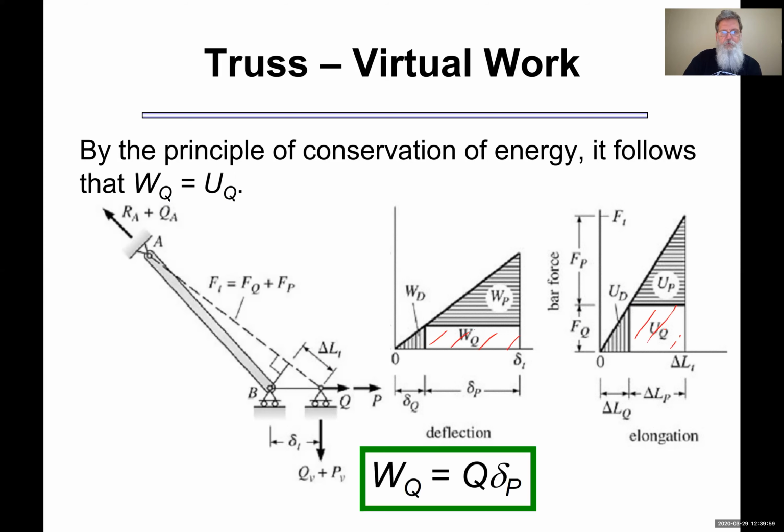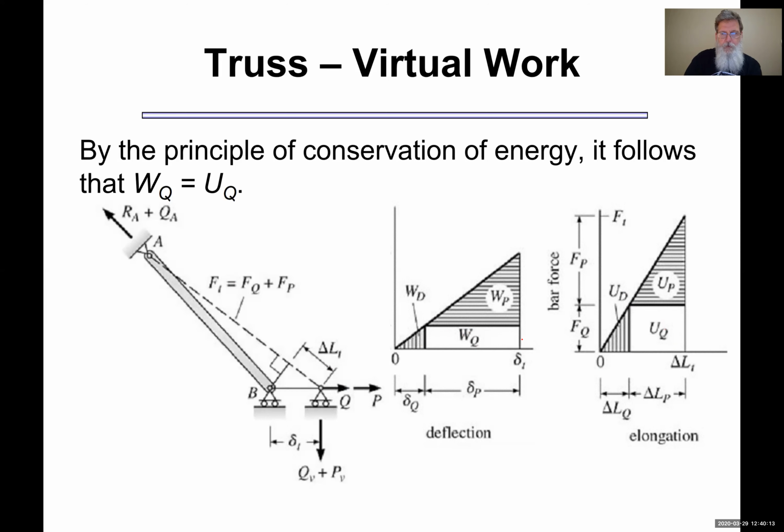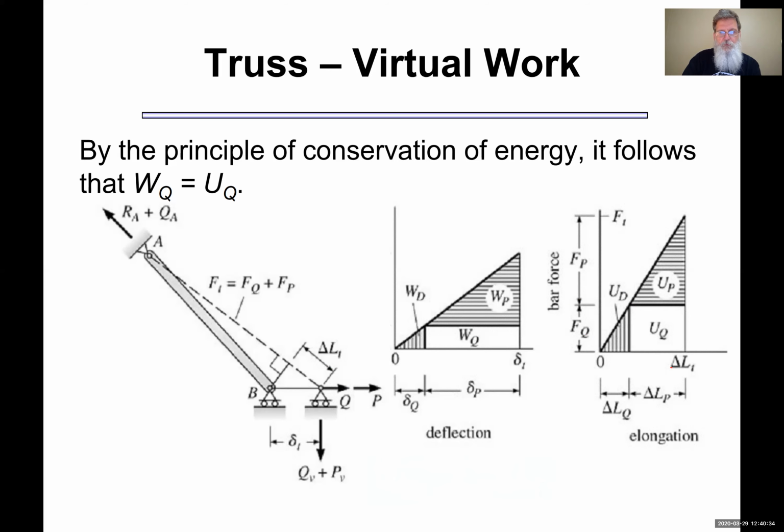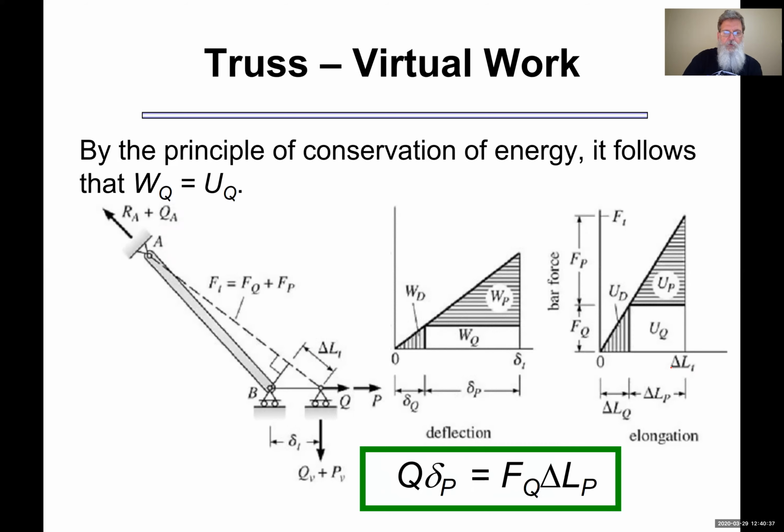Oops, sorry, I went too fast. So now the real work done here is a virtual force Q going through a real displacement. That's the area of that thing, base times height. And the same thing is true for the strain. So I've got a virtual force FQ going through a real displacement. So let's see how that adds up. So now I put those two things together. So now look on the left-hand side.